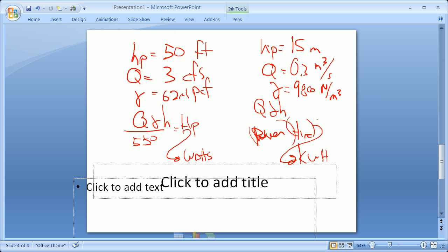All right, so that's a lot. It just is why, when you go through hydraulic head, you want to at least have looked at the pumping stuff, and pretty straightforward things that we're looking at here is the velocity head, which is velocity equals the square root of 2gh, being something you've seen in physics and something that we have to realize is a good part of Bernoulli's equation. A lot of Bernoulli's equation is trading: the amount of energy you have gets traded between elevation, pressure, and velocity. So if you have a lot of pressure in a system, you might have less velocity or vice versa. Thanks for listening.